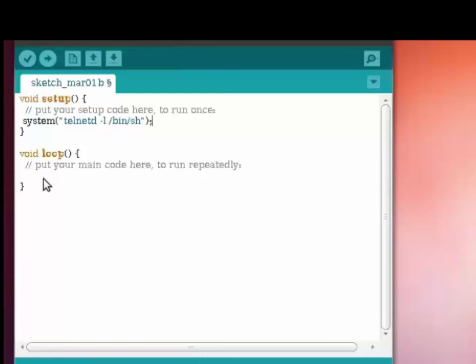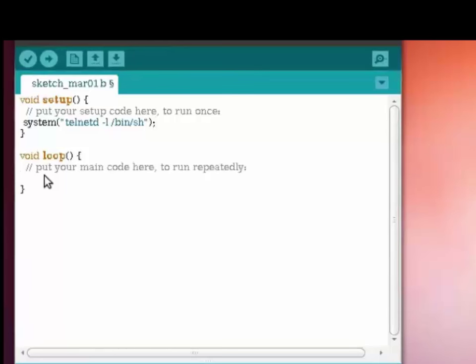Once the application is started on Galileo's OS, the IP address is assigned dynamically by the DHCP in the router, and we just need to echo the IP address from the Galileo's operating system and view it on the Arduino Serial Monitor window. So we will issue a system command ifconfig eth0 and redirect the output to /dev/ttyGS0. We will also provide a delay with sleep 10.